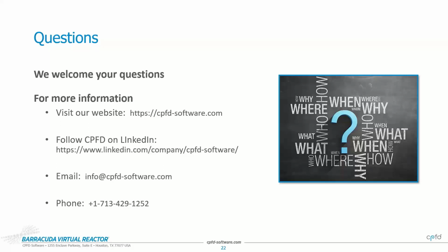And one thing that I forgot to mention, but is definitely worth mentioning, is that it does not have a very high computational cost either. Based on some timing tests that we did, if you run with the dynamic distributor feature turned on, it has a very negligible impact on runtime. So it's a very safe feature to enable. As long as you are properly defining your velocity and your orifice discharge coefficient, it can only make things more realistic for most simulations.